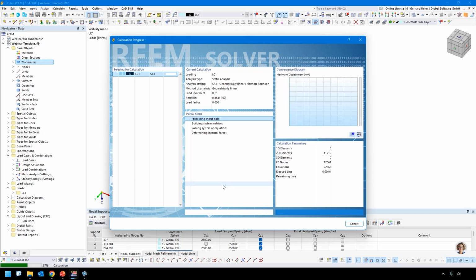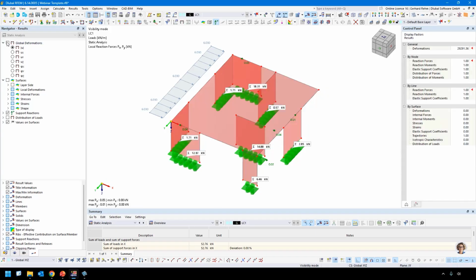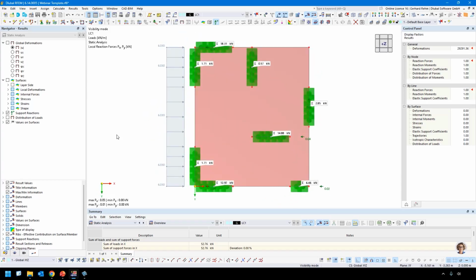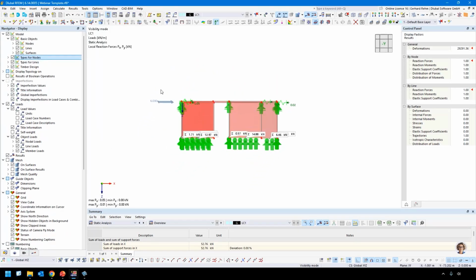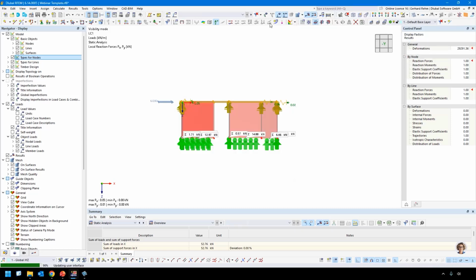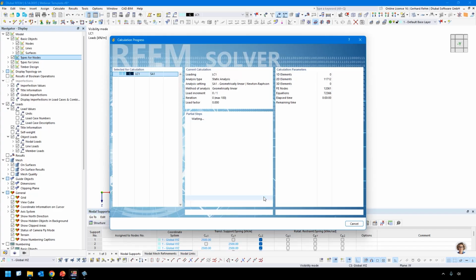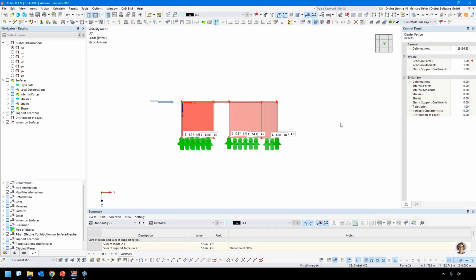And then let's check the forces, how they will be distributed, hopefully in the same way as in our simplified approaches. Same deformation. I don't care about deformation. We haven't defined the correct stiffness, so we cannot check any stiffness in this approach. But what we can do is, yes, I did, sorry. I have not deleted the nodal supports here on top. Nodal supports, delete assignment, yes, okay. And of course, I expect the same results in this case as for the simplified methods.